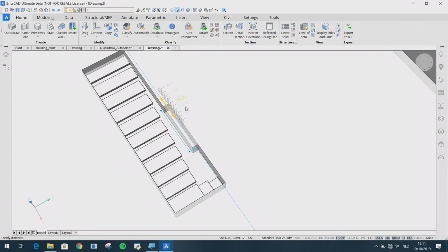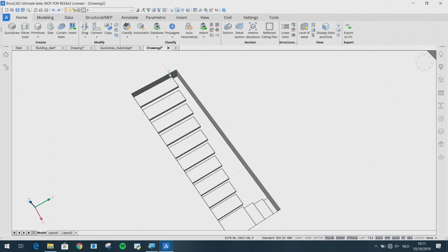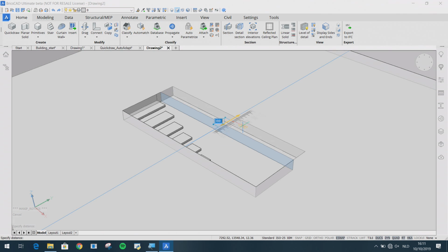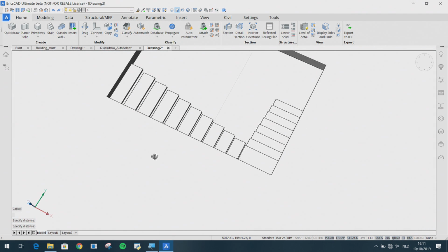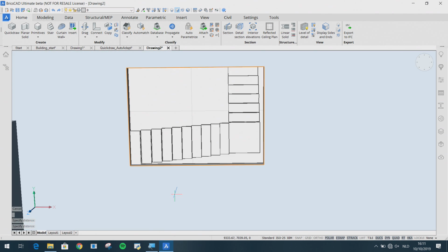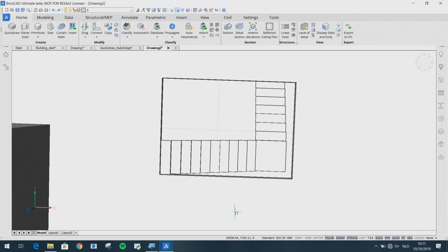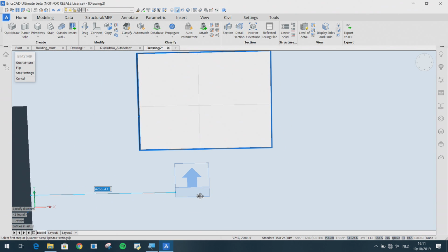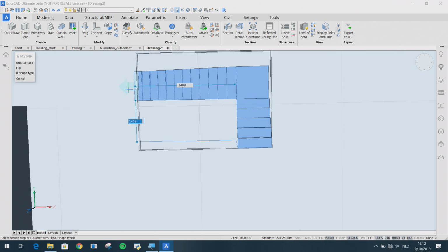This is kind of a minimal opening you need for the headroom you need to walk on this stair, and you can just start modeling from this opening to modify it to the specific needs for your project, for your building, which will be different each time. Walter will also demonstrate the last snapping feature of this stair cursor, which is to the edges of existing openings. So you can also start your stair from an edge of a slab, an edge of an opening in a slab, to quickly create it.